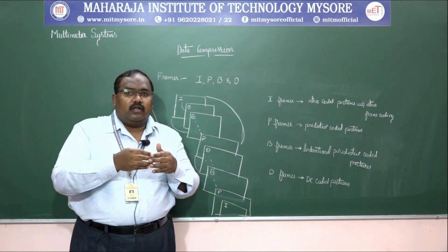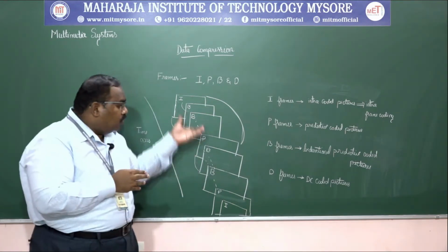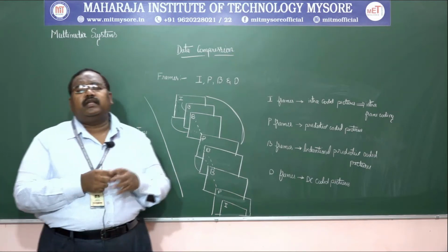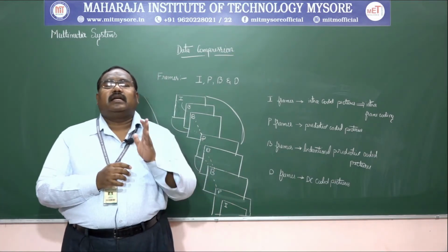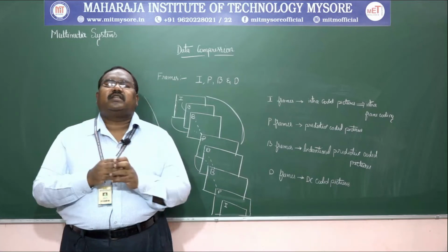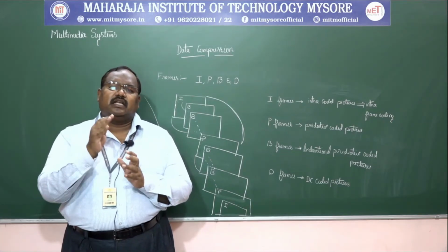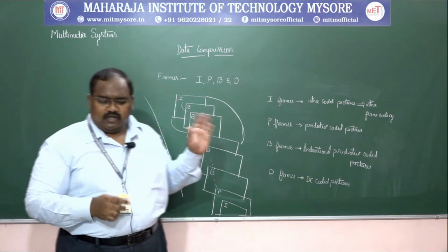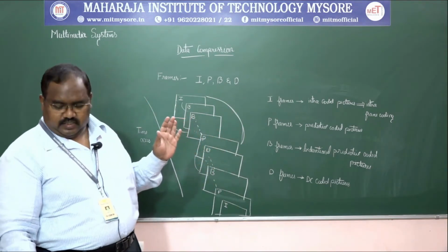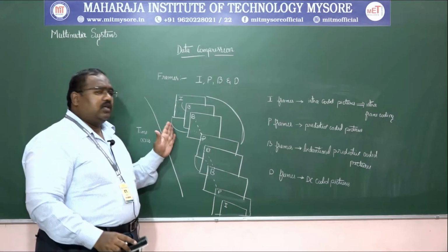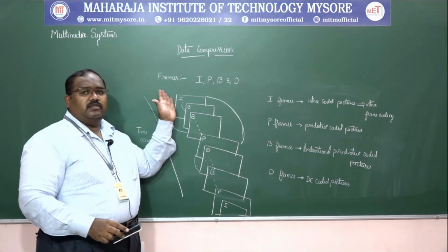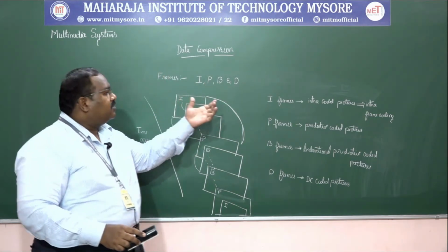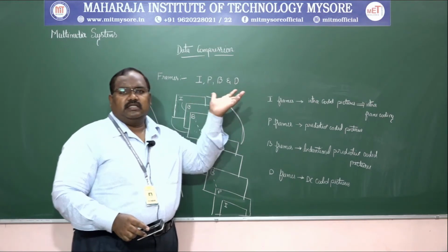It means that in order to have the fast forward technique, to move directly from one frame state to another, in the D frame only the DC coefficients of the DCT are coded, and the AC coefficients are ignored. So in order to have the fast forward concept, we use these kinds of DC coefficients, that is, we call them D frames. So these were the concepts with respect to the frames: the I frame, P frame, B frame and D frame. D frames are very seldom discussed.